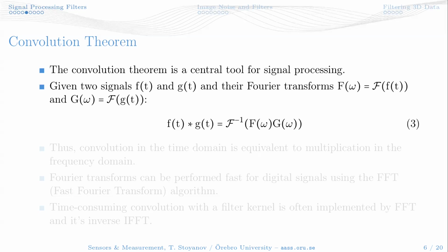So my signal processing professor was always saying, if you want to do a convolution, you just go to the Fourier domain and you multiply. That's it, right? So in signal processing, this is a common way to filter. Instead of doing filtering in the time domain, you take the frequency domain version of the signal and you multiply it with the filter in the frequency domain and just take the Fourier transform back.